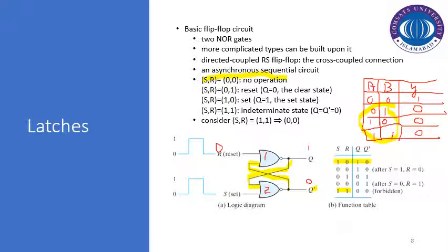It means S equals 0 and R equals 0, and the latch is already in a set state. Now if you observe the table here for this NOR gate, we have the inputs 0 and 0. This 0 was the output, or the status of Q prime, that's already stored. So the next output that has been generated by applying this 0 and input 0,